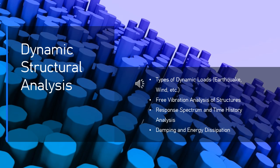A response spectrum is a plot that shows the maximum response, typically displacement or acceleration, of a single degree of freedom system to a particular input excitation, like ground motion during an earthquake, at different frequencies. In simple terms, it is a graph of the maximum peak response of structures of varying natural frequencies, or modes, when subjected to a specific dynamic load.